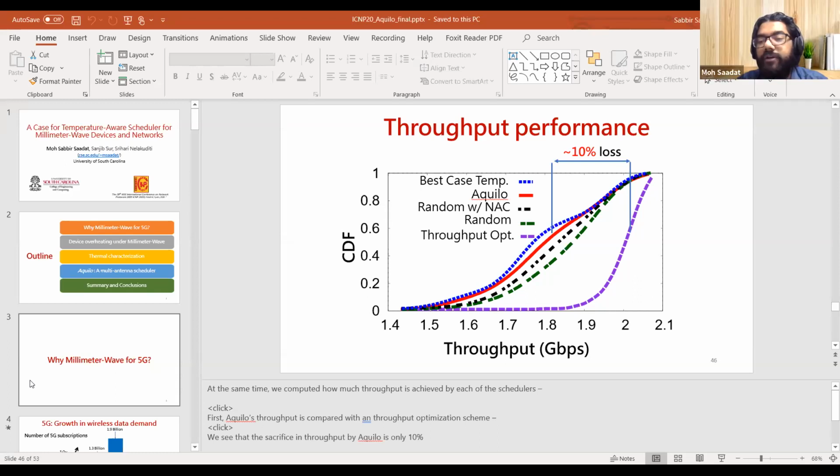You mean, did we check experimentally? We didn't practically check for blockage, and we ensured that there was no blockage when we took the measurements. When working with the measured data, we modeled blockage: at any given time, an antenna has 0.1 probability of blockage. We didn't actually block an antenna. We ensured that there was a channel when we took the measurements, but when we simulated the results, we modeled a blockage probability.